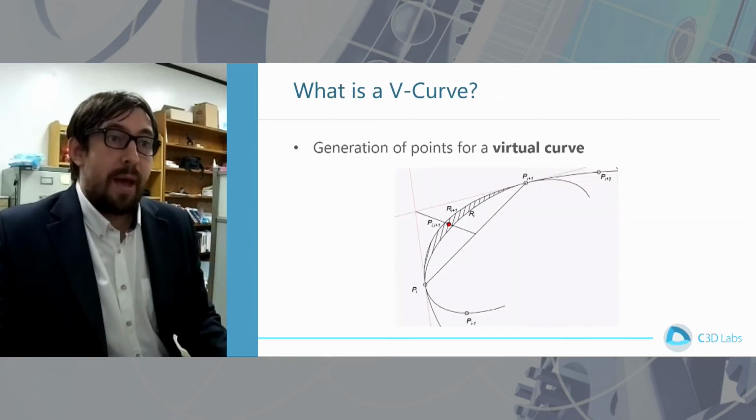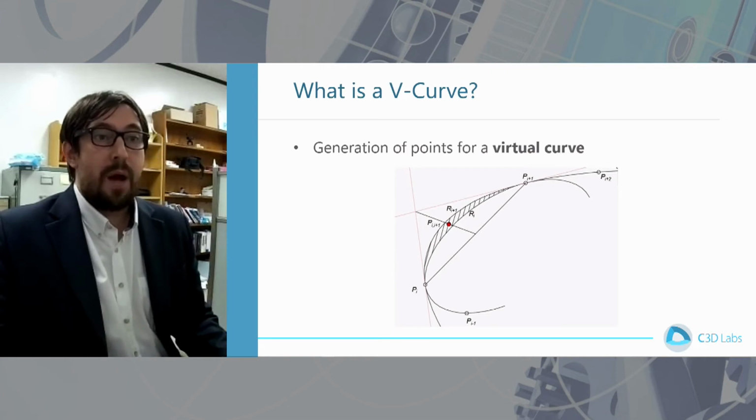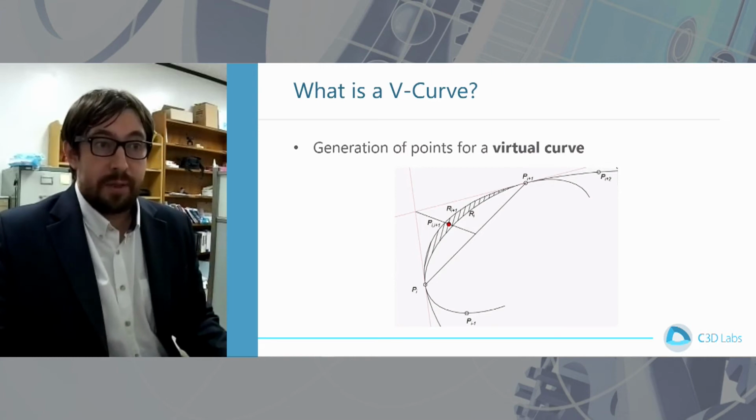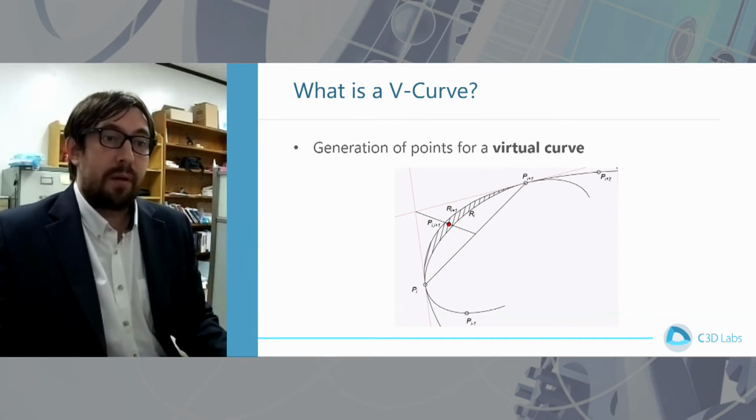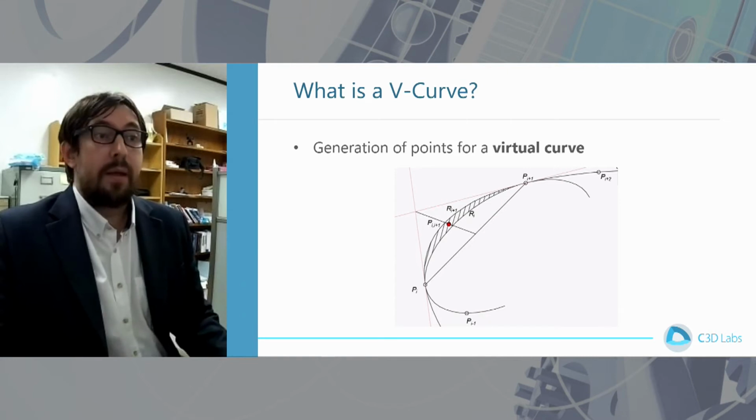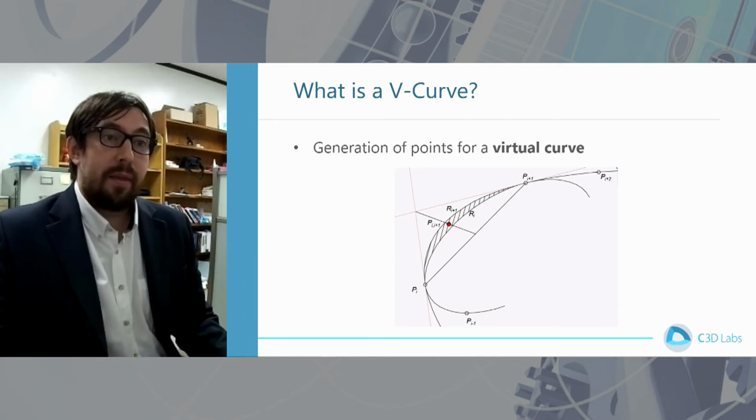The math behind C3D FairCurveModeler is based on parameterization. With it, we generalize the concept of the spline as a set of curves having equal geometric parameters at arbitrary points of the base polyline. In conventional splines, the parameters of the curves are equal only at the spline's segment junctions.